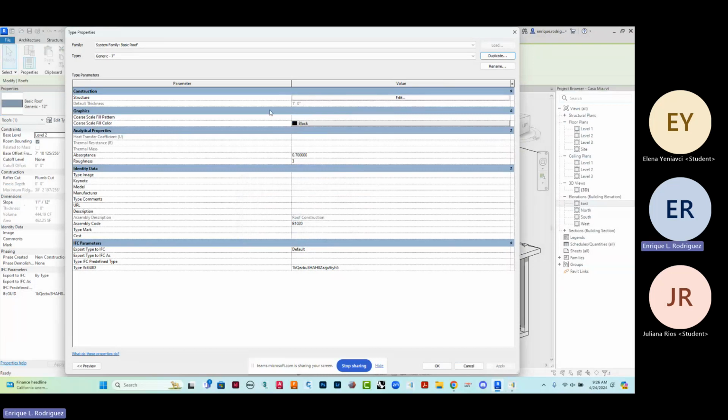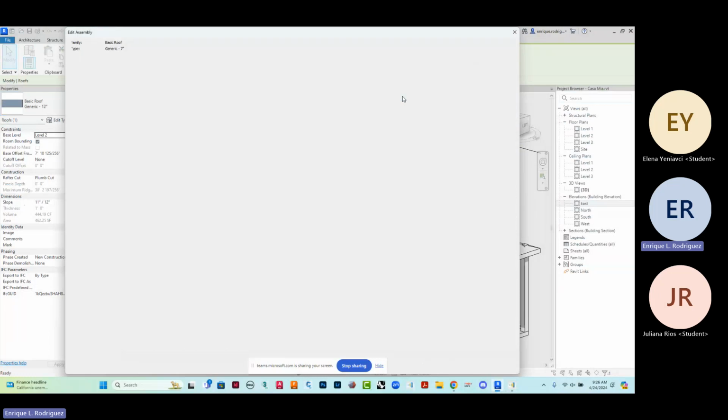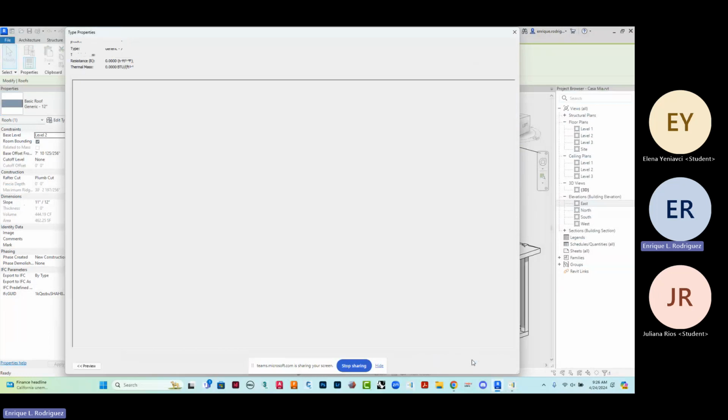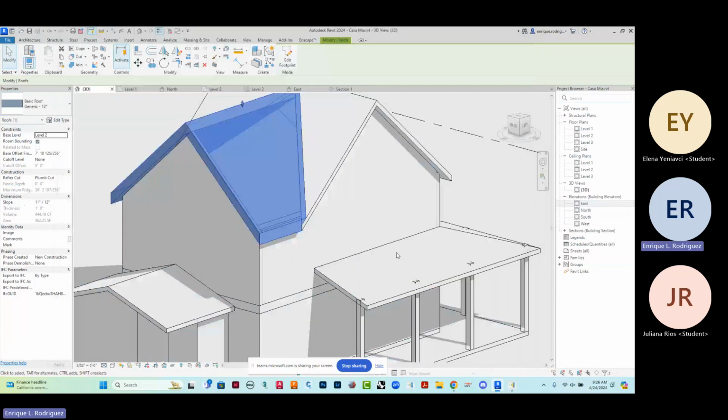And then I still need to come in. If you notice, the default thickness is still at 1, but it's grayed out because you have to go in here, and then you change the value right in there. I'm going to go ahead and cancel, because I really don't want to create that one. And I'm going to bring this one back to a generic 6.